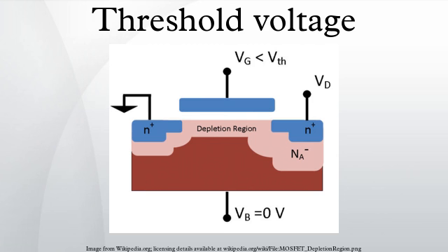In contrast, N-channel depletion mode devices have a conductive channel naturally existing within the transistor. Accordingly, the term threshold voltage does not readily apply to turn such devices on, but is used instead to denote the voltage level at which the channel is wide enough to allow electrons to flow easily. This ease of flow threshold also applies to P-channel depletion mode devices, in which a positive voltage from gate to body/source creates a depletion layer by forcing the positively charged holes away from the gate insulator/semiconductor interface, leaving exposed a carrier-free region of immobile, negatively charged acceptor ions.